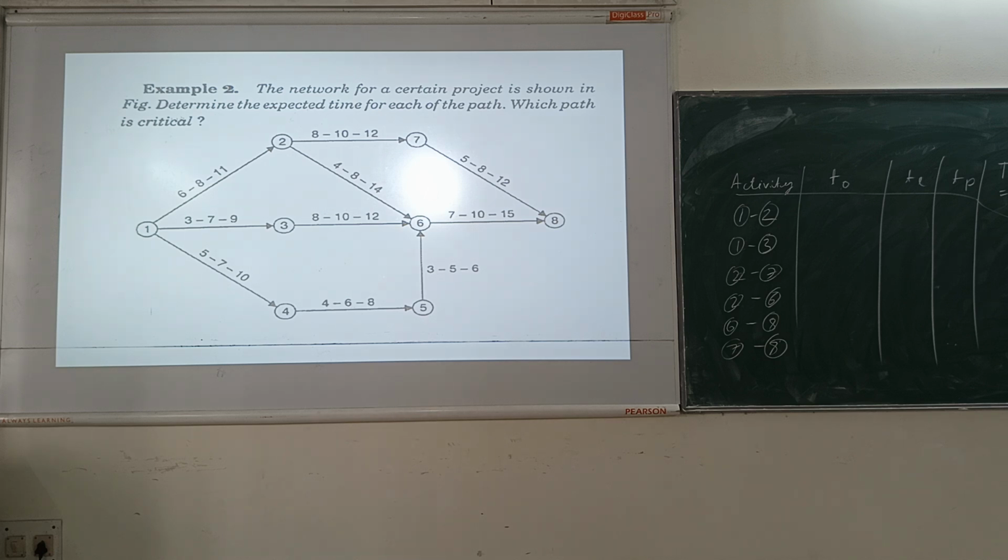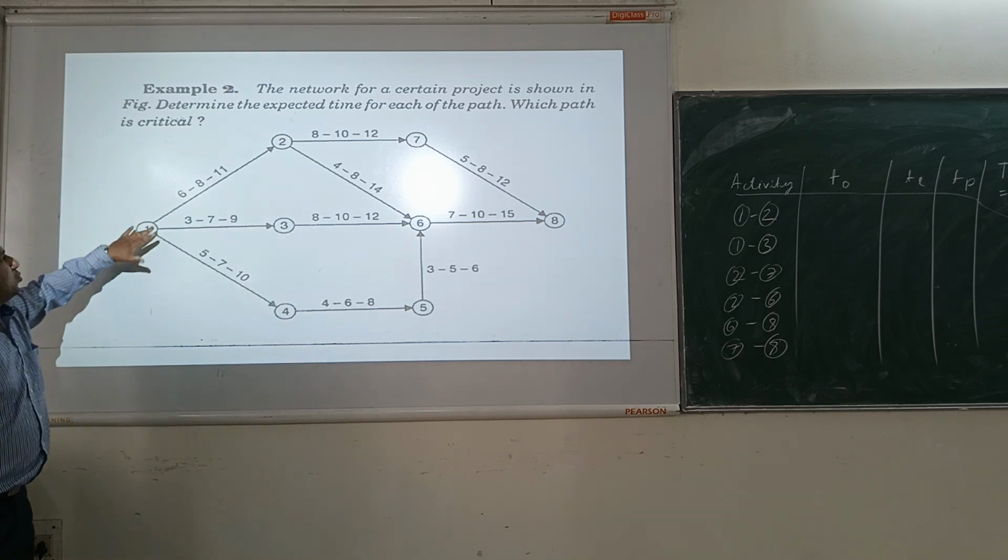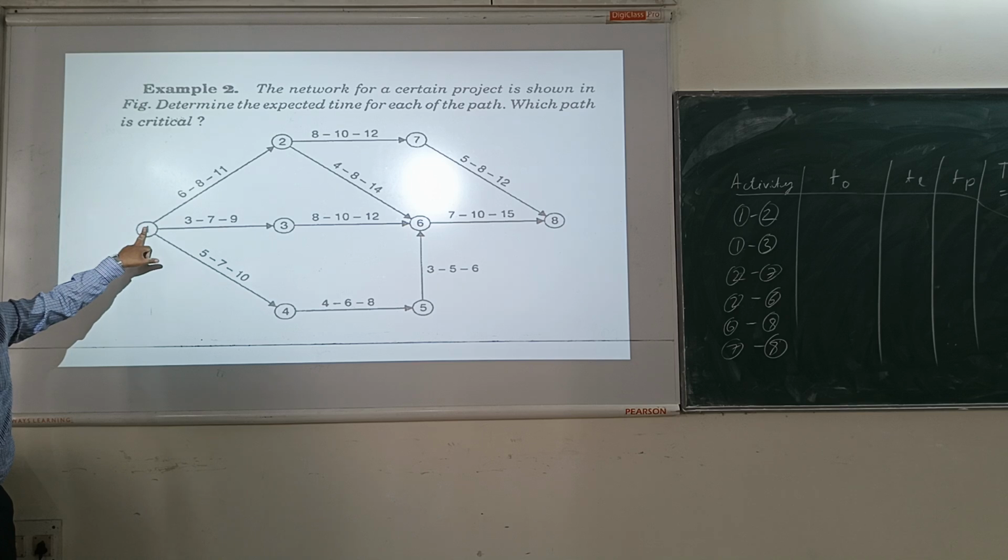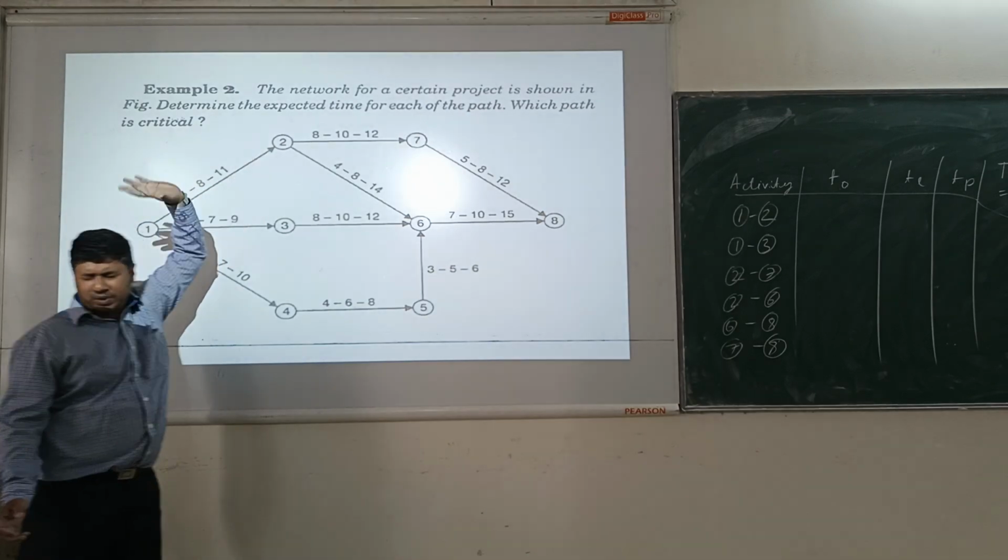Most optimistic time. Then there is most likely time. Then there is most pessimistic time. Optimistic time means the minimum time required. For this activity, suppose 1 2 3 is excavation. Excavation has started. Excavation will complete.